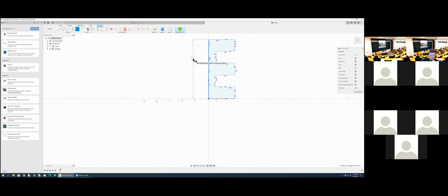Instead of adding those black lines, why can't we just fix it? Because fixing is cheating. Fixing doesn't count as actually fully constraining your object. It's not fully constrained. It just doesn't move. I don't know if I can make an equivalent example, but it's just cheating. Don't do it. Yes, there you go.